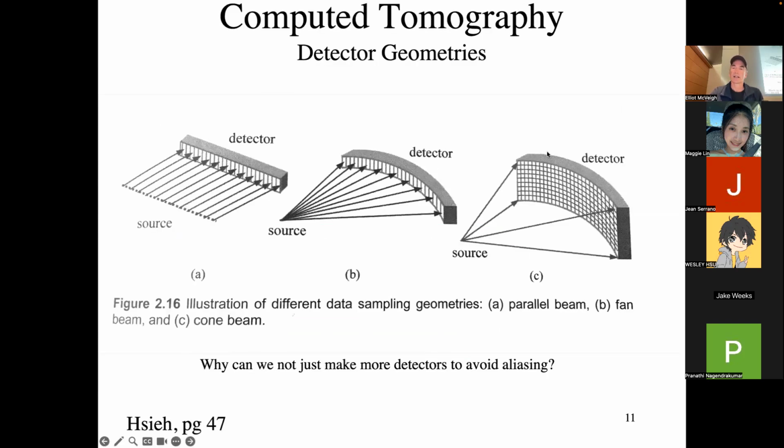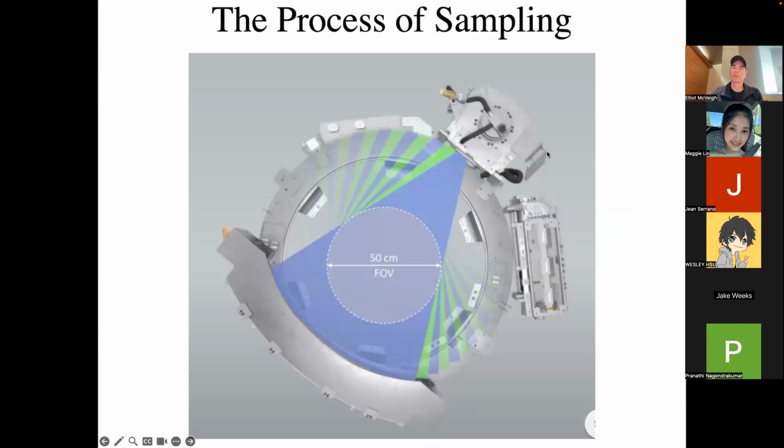Okay, so that's our fundamental sampling rate in CT, set by that detector. You can imagine there is a push to make the sampling rate higher, so you could detect higher frequency or sharper edges and things like that. In CT, the problem with continuously making more and more samples along your detector is that eventually you run out of photons for each spatial unit.